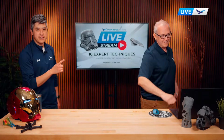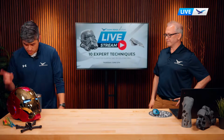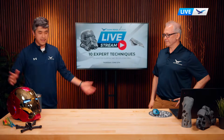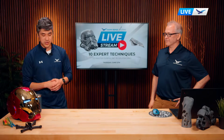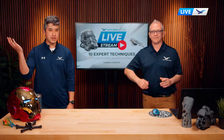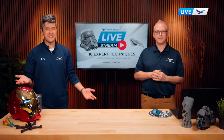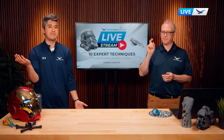I do want to take a second here before we go to the next one, just to take a look at the chat a little bit. Number one, Cayman Frederick, thank you very much. That's a great tip. They're saying right-click on a surface and try to make a sketch, and if the create sketch button shows up, then it's flat. And I do that all the time, where I'm not even trying to make a sketch. I'm just seeing if it will give me the option, right?